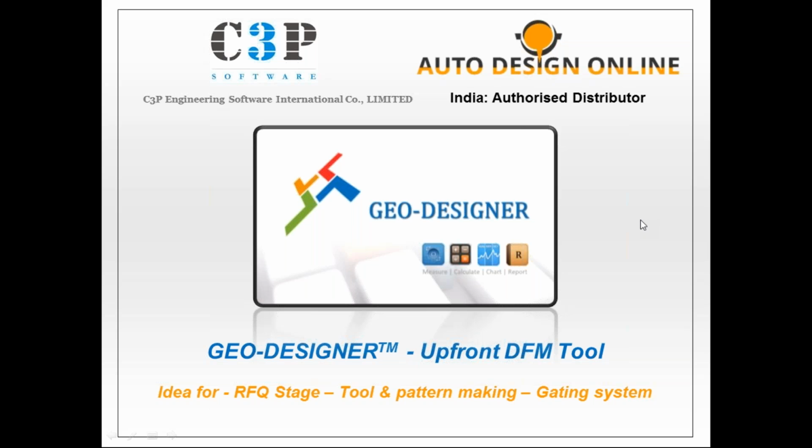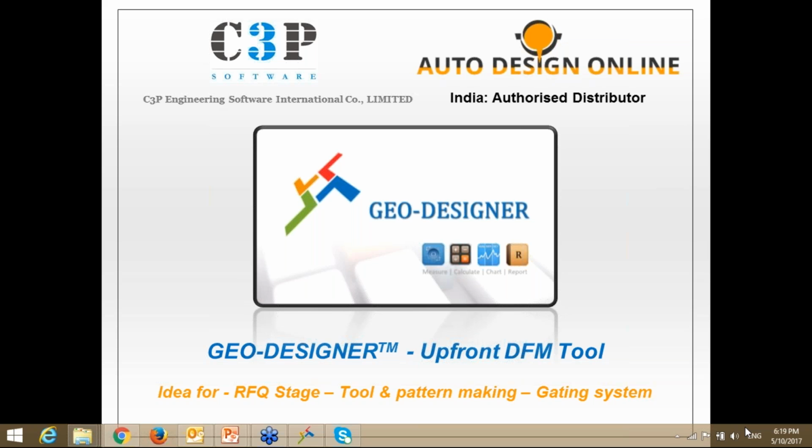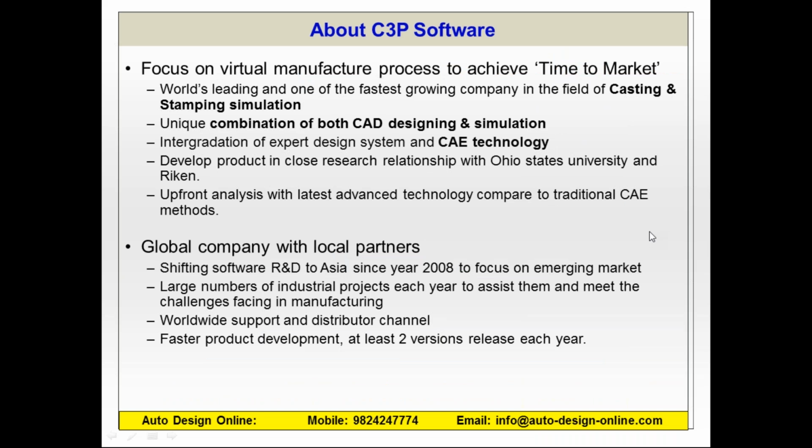So these kinds of questions can be answered by the DFM tool, which is not actually a simulation tool, but will be useful for the designer at the early stage to decide quickly about the gating system, and so forth. So the purpose of this is how we can do this complete requirement analysis of different casting parts and their geometry.